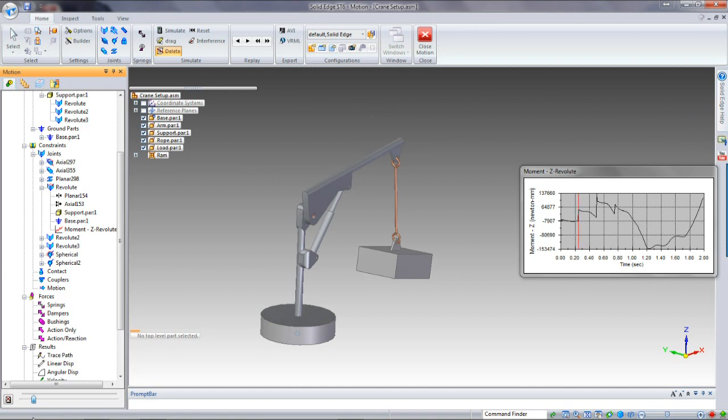As we come to the first spike, it's where the revolve starts to happen. As I come to the second spike, it's where the hydraulic ram reaches the top of its lift. And I can't help but wonder if that particular spike there is because it was rising quite rapidly. All of a sudden it stops rising, and just maybe it rises a bit further and then sinks back onto the ram. So that could be the cause of that spike.